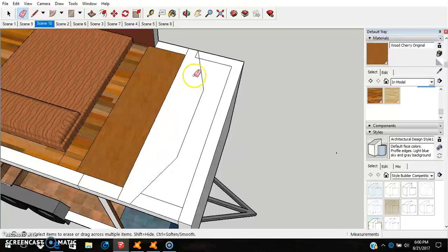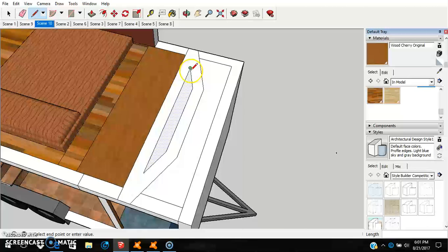What we're doing now is really, I believe, the best way to determine your outside wall, or to get the proper measurements, the 6-inch thickness of that wall. So we're using the offset somewhere here, and just enter 6 inches, and then continue these lines.